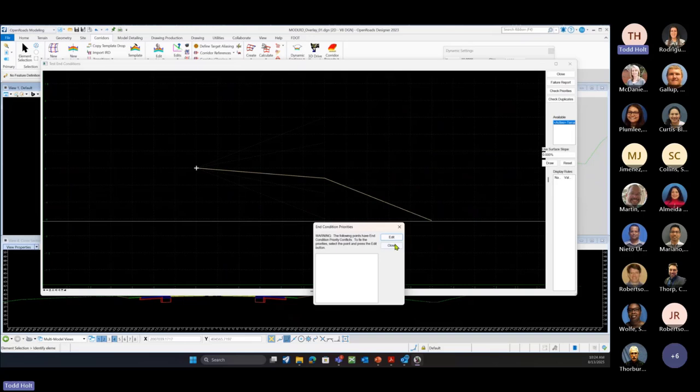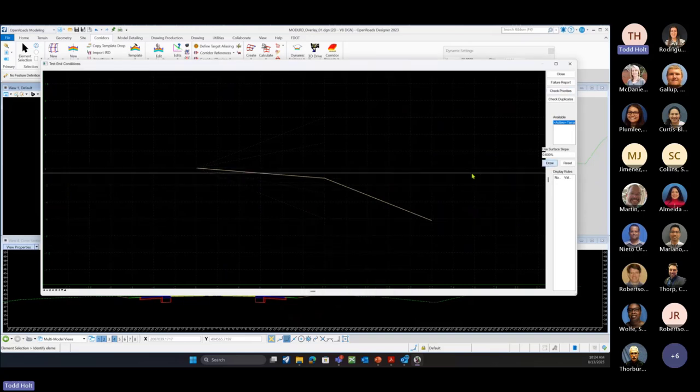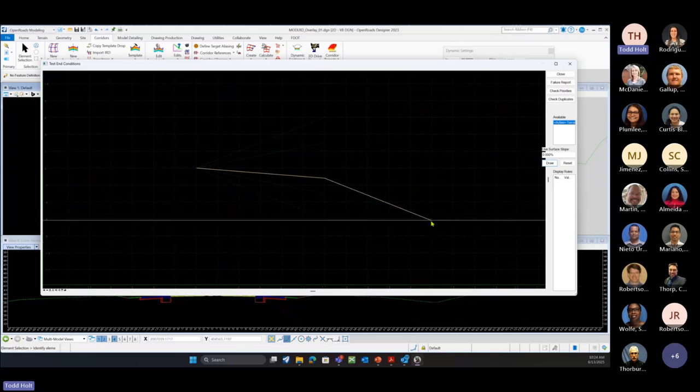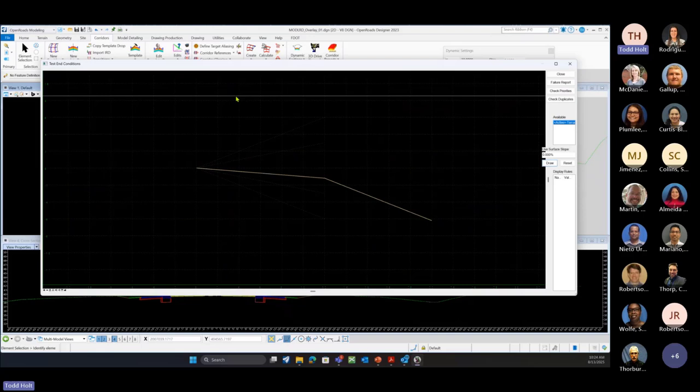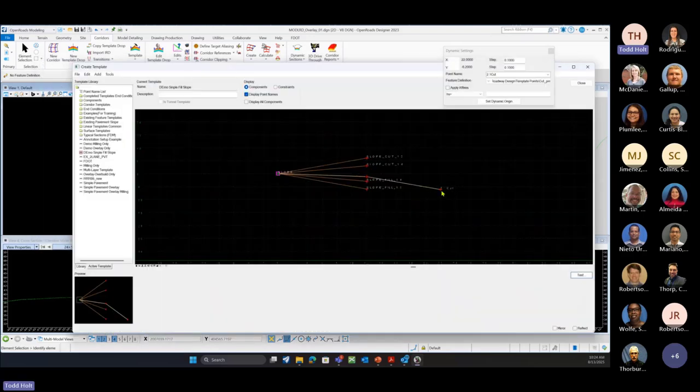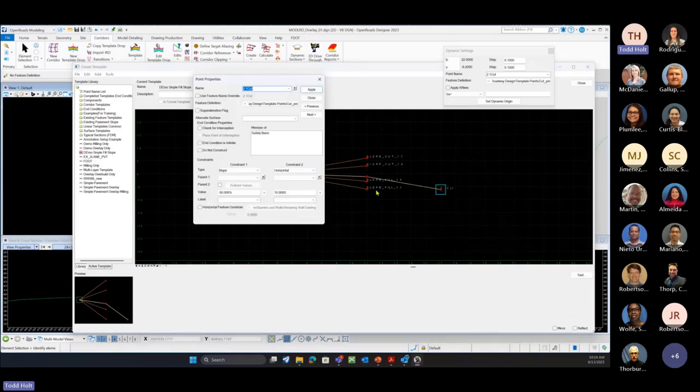And then if I click OK and close, so now if I draw this and test, it's always going to draw that one, because it's finding existing. Would need to have it set in there. So I need to go and check my other points in there, and then it's going to move on. So if I look at this guy, I need to check for intercept, place point intercept on that endpoint.